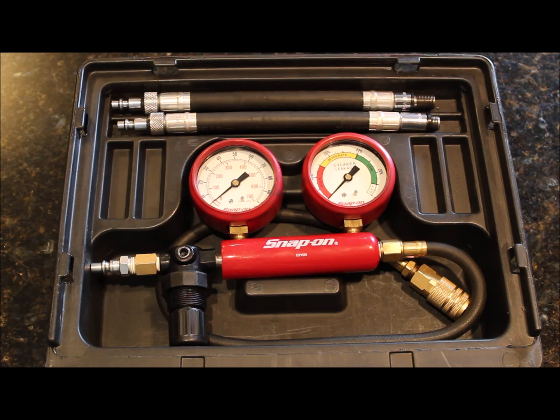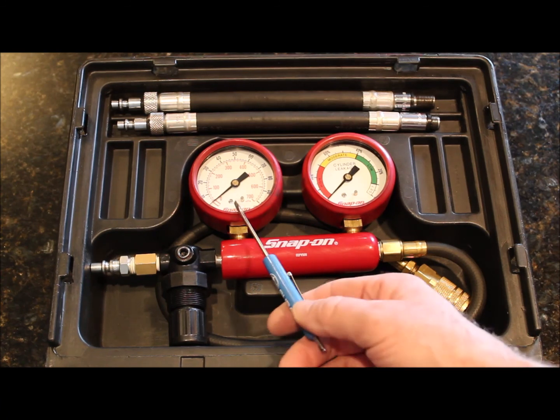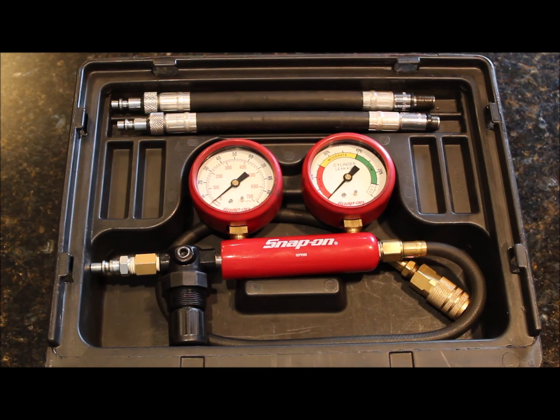But the basic procedure, and we did it before, is you blow air into the cylinder at a set pressure. You see how much pressure the cylinder holds. There's always a little bit of leakage. Anything up to 10% is absolutely normal. A brand new engine would do that. Now, when you get above 10, it indicates you have some leakage, and if it's 20, 30, 40%, you've got a fair amount of leakage, and that could start affecting your compression, definitely.